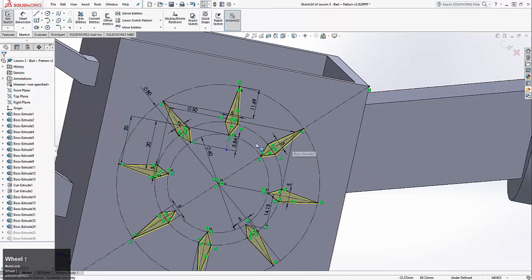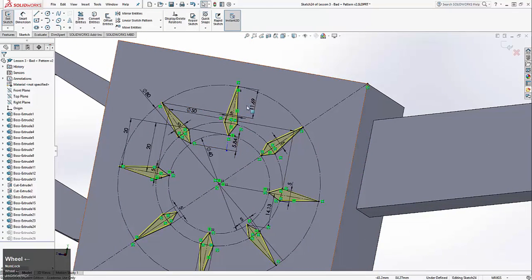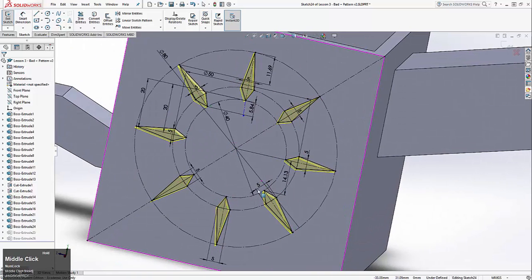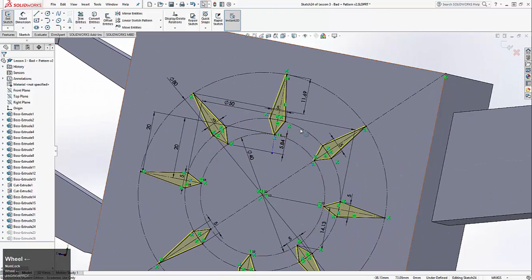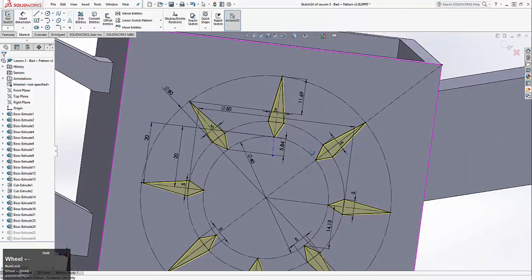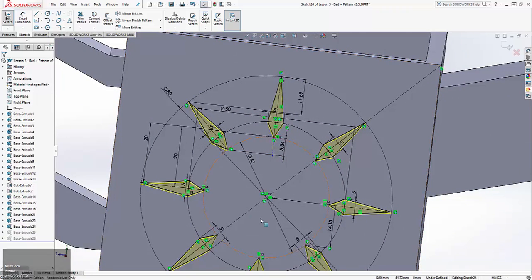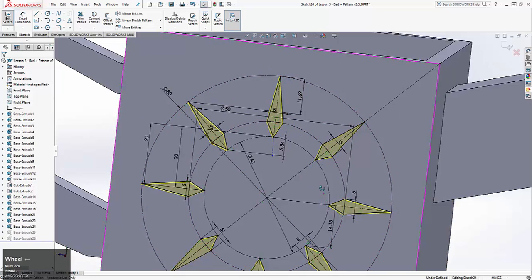So we got the sketch, and there's a lot going on here too. So once again, instead of doing every one manually, they had a stroke of brilliance for a moment compared to the rest of the watering can. They use these circles for construction at the different points along the diamond. So at the first point, they're all going to be at the same distance from the center because they're all along this circle. Same thing with these points, they're all along this construction circle, and same with the final points. And then you dimension the circles, and that's essentially dimensioning all of the points along there.